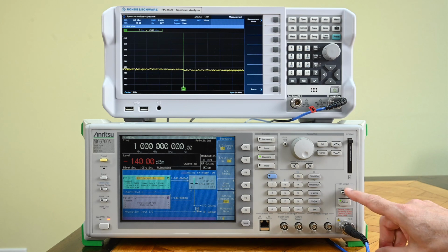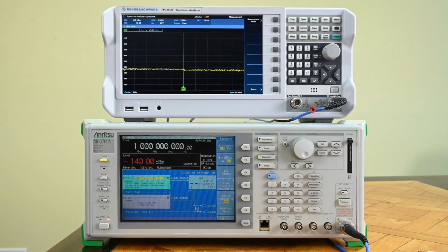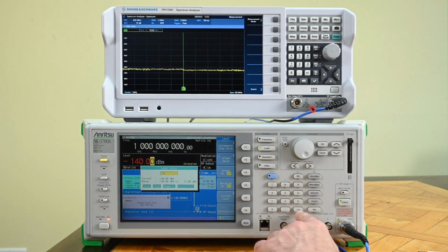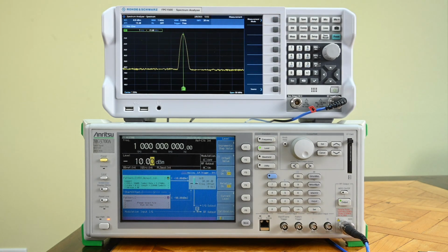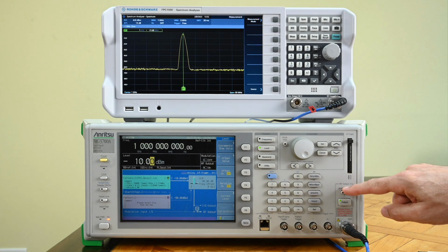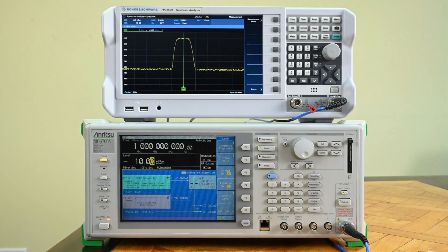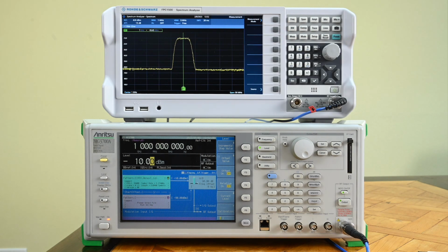The output is on, nothing is modulated yet, but I don't see anything yet because we're still at minus 140 dB. So let's put the level at minus 10 dB or so. Yes, and we see our carrier waveform arriving here, unmodulated, and we're going to modulate that signal. And yes, this is the type of signal that we expected, a relatively broadband signal.